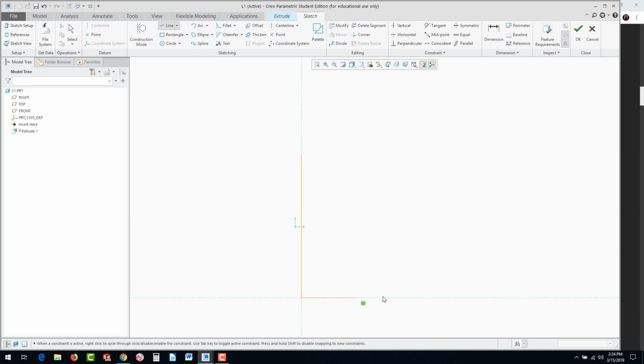Okay, now I'm going to click this and drag this out to the right. And then I'm going to drag this up a little bit here, go across here, go up, and I could infer to that line there. That's a little inference line, you see. Drag this one down. Be careful. Look at this. There's an equal symbol to the right of my pointer. Stay away from the equal symbols. There is a way to turn them off, actually, in the options.